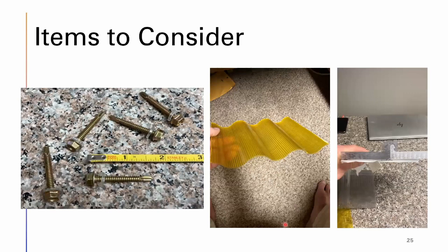Now, mainly what we're going to talk about, I'll show you some pictures of the panels, but you need to consider your screws. I ran out of screws actually on that 4,300 square foot greenhouse. So I had to go to Tacoma Screw. I was paying, I think, 13 cents a piece. I actually sell these for 8 cents a piece. But you can buy them. I use them between 1/2 inch to 2 inches long, depending on what I'm doing. If you're using steel, these are self-tapping screws.